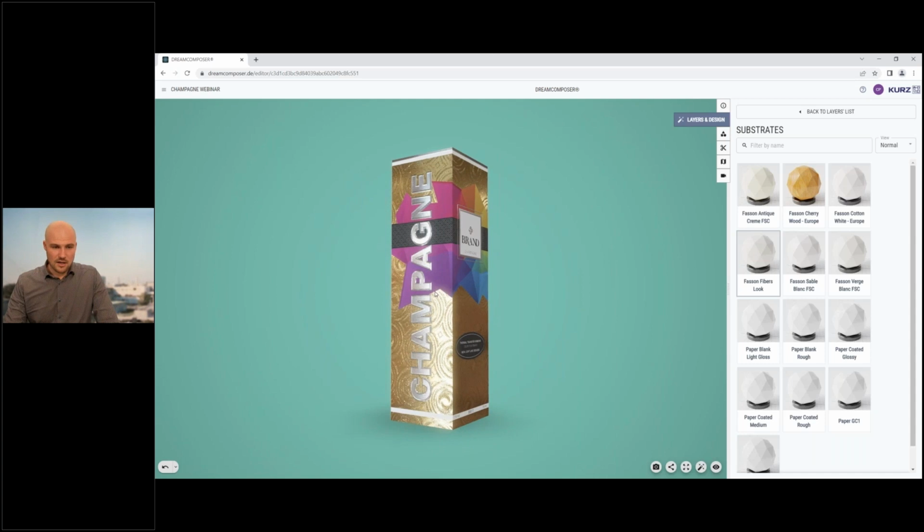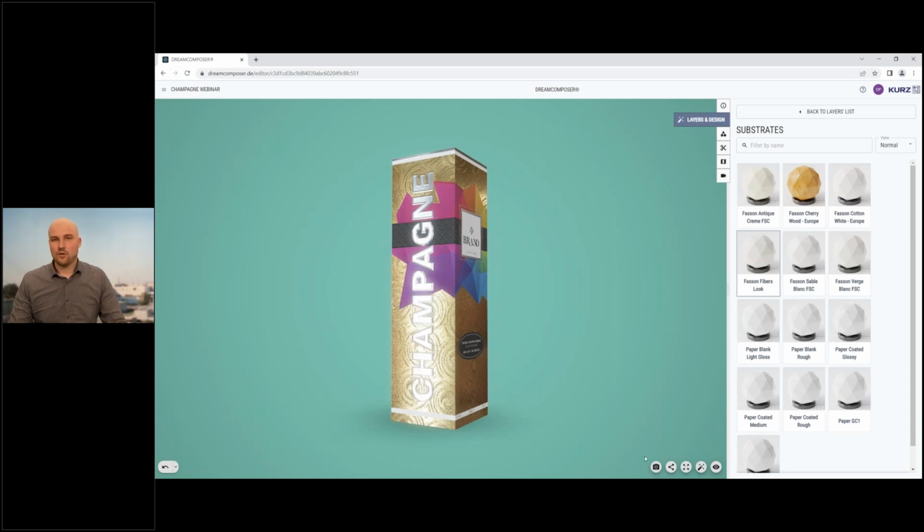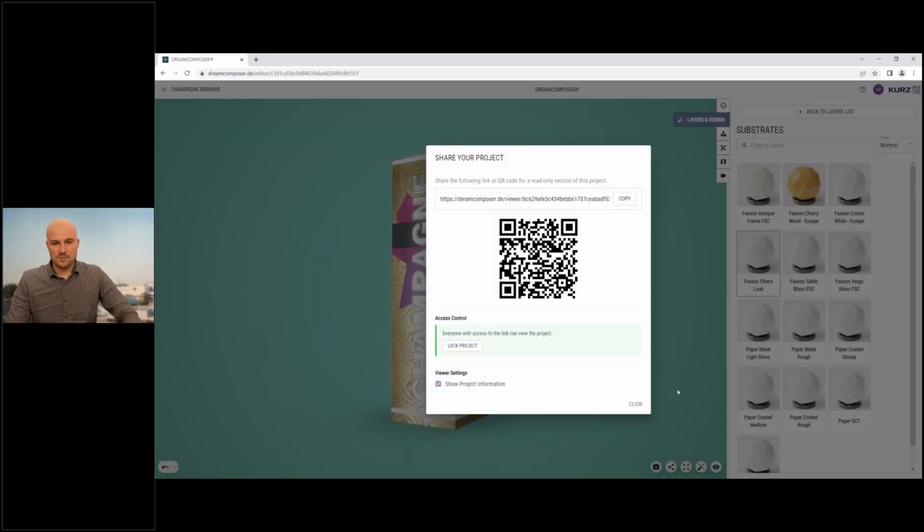You could create a 4K screenshot by clicking down here at the camera icon. Then a 4K screenshot is created of this project. But we really enjoy when you have that dynamically, so you could have a share link and then view it. We do have that possibility down here to press that share icon and give people the opportunity to share their project via that link.